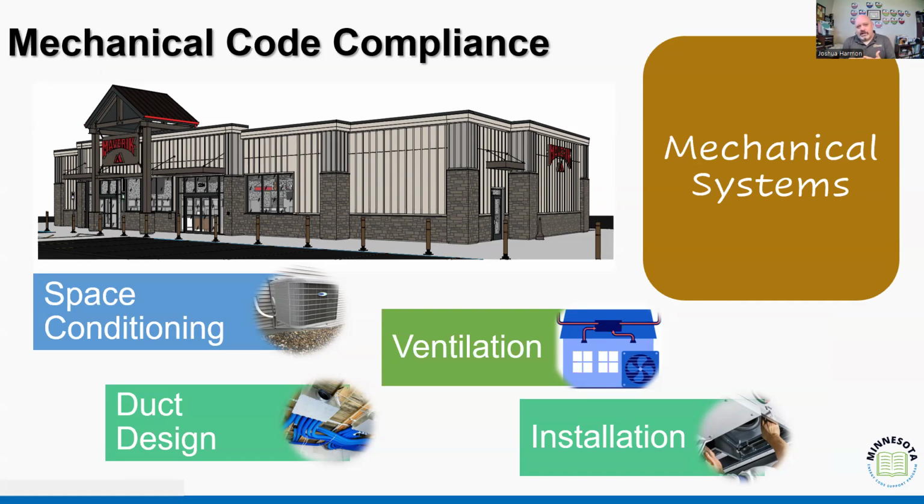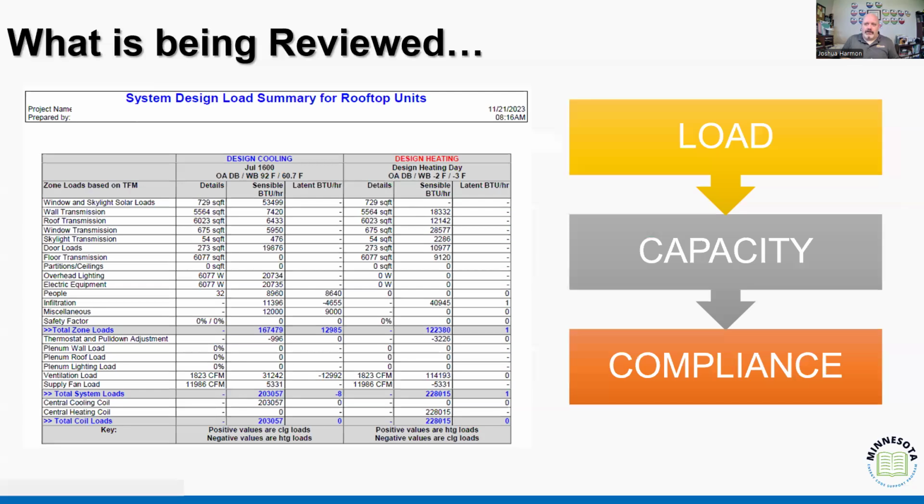Now, the same way we've talked about before, my job is not to go out and rerun all the calculations, right? I'm not getting the mechanical load calculation and then rerunning it myself at the office. I'm a plans examiner. My job is to make sure that you did a load calculation. I'm looking for certain variables. We'll talk more about that when we get into mechanical design here soon. But I look for that load calculation. I verify that the equipment has the capacity to meet the load, and then I'm done, right? That's how I verify compliance.